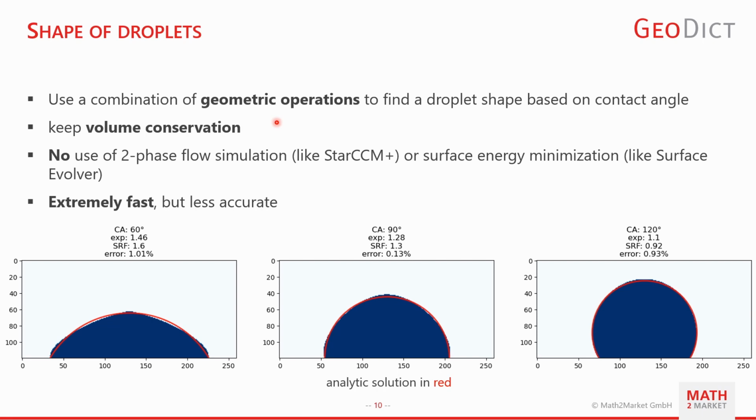And we decided to do this because we do not use two-phase flow simulation like StarCCM or surface energy minimization like Surface Evolver, which will give us an extremely fast solution. On the downside, we have a little bit less accurate solution at the end. As you can see here, the analytic solution in red is a little bit different than our solution, but I think it's still quite a good match.